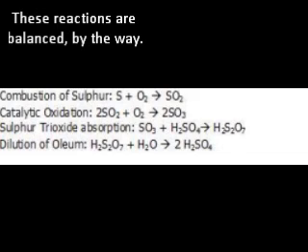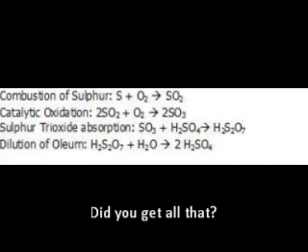Overall, the following reactions occur. The combustion of sulfur, which is sulfur reacting with oxygen to form sulfur dioxide. The catalytic oxidation, which is sulfur dioxide reacting with oxygen to form sulfur trioxide. Sulfur trioxide absorption, which is sulfur trioxide reacting with sulfuric acid to form oleum. And the dilution of oleum, which is oleum reacting with water to form sulfuric acid.